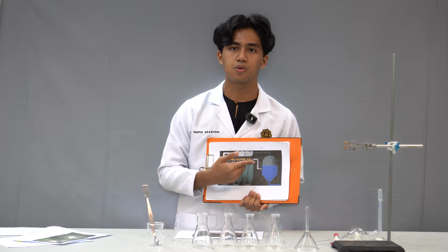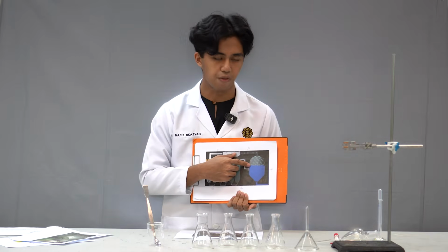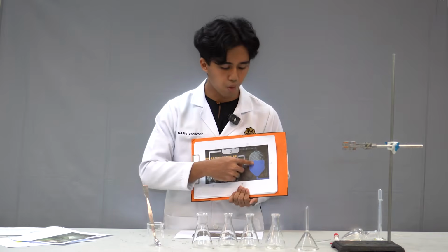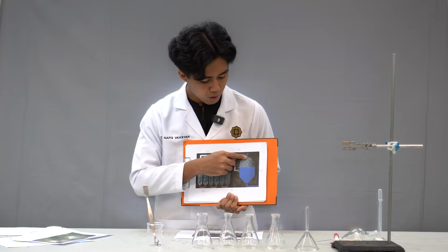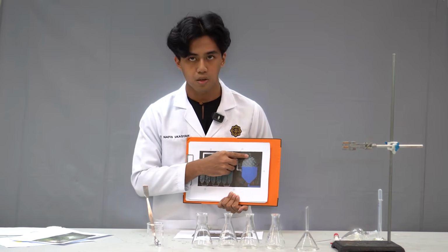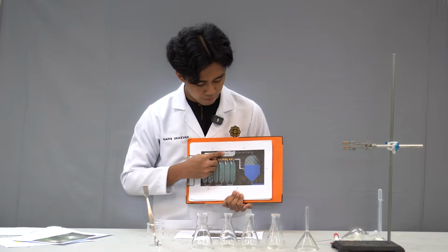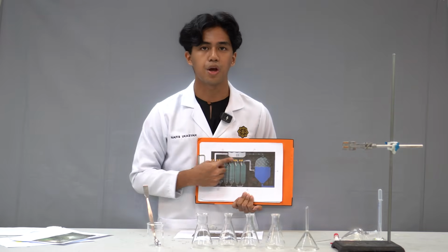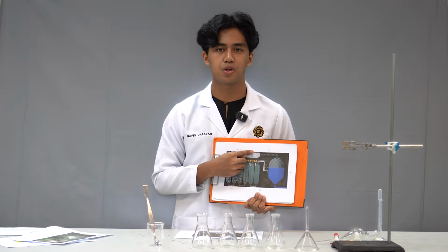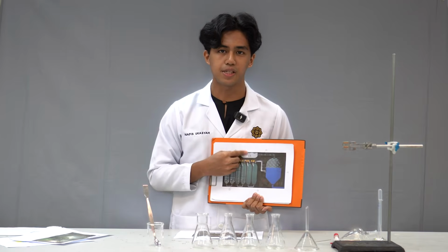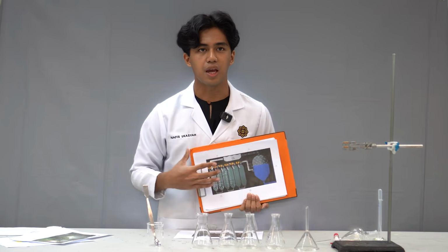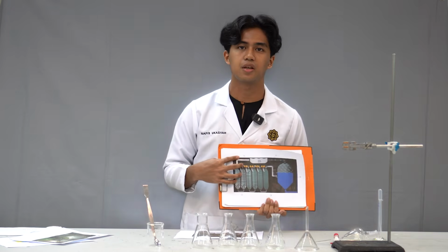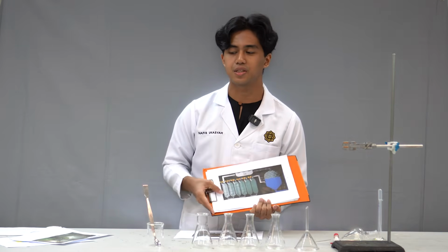At this state, CO2 is no longer able to carry the caffeine, so it releases the caffeine to the water. At the next step, the CO2 gas goes through and goes to a new column. At this column, CO2 gas is condensed back to liquid and goes through the cycle again. This cycle continues until the desired caffeine level is reached.